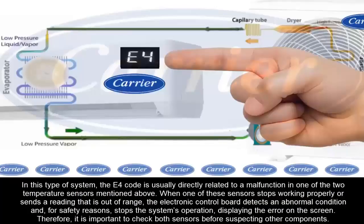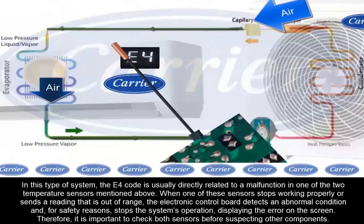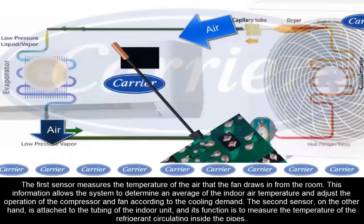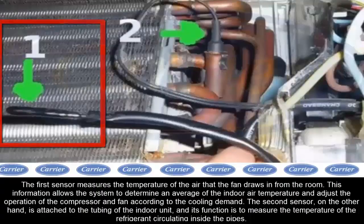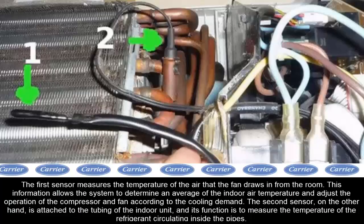When one of these sensors stops working properly or sends an out-of-range reading, the electronic board detects an abnormal condition and, for safety, stops the operation of the system, displaying the error on the screen. Therefore, it is important to check both sensors before suspecting other components. The first sensor is responsible for measuring the temperature of the air that the fan draws in from the room. This information allows the system to know the average temperature of the indoor air and adjust the operation of the compressor and fan according to the thermal demand.